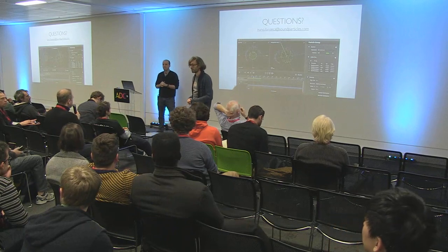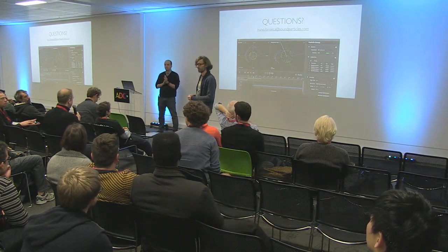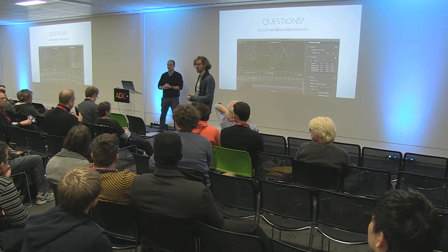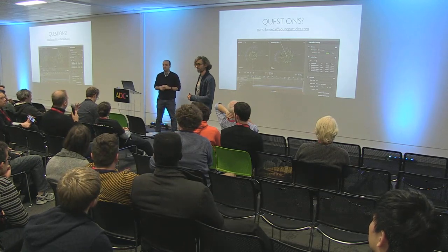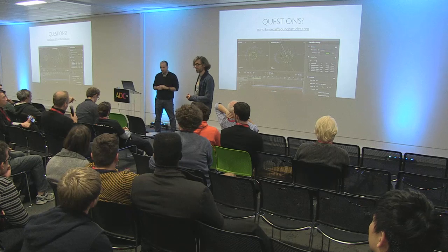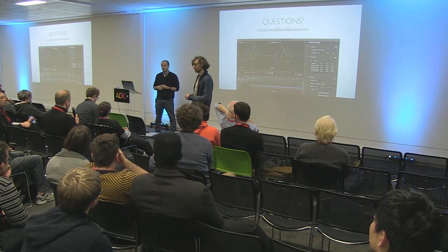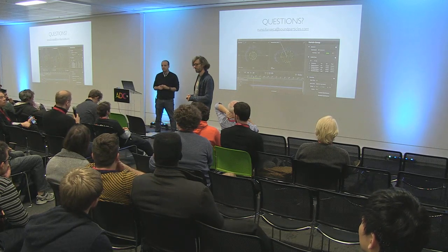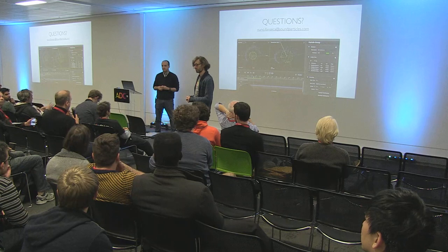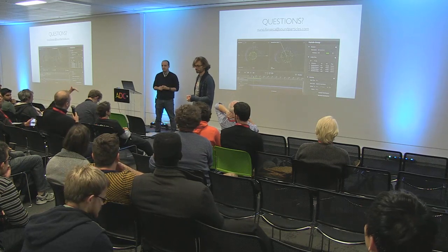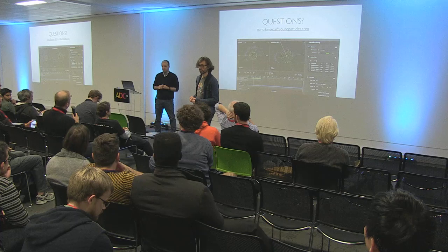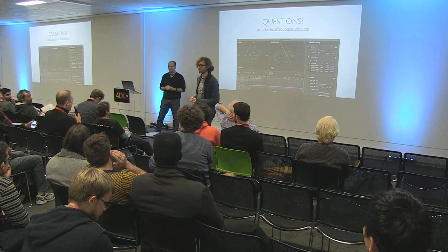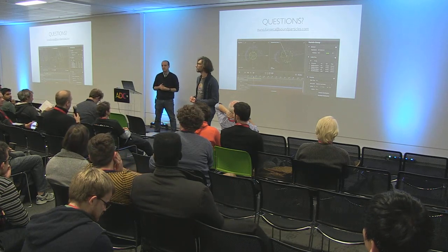Thank you very much. Very interesting talk. I have a question. I'm not sure it will be interesting for everyone, so if not, please let me ask afterwards. But what was always bothering me: you mentioned in the beginning this panning law, which is kind of linear with a -6 decibel drop. I know this explanation works perfectly for crossfading, and I also know it works in practice for panning, but I always thought that in panning you would basically apply gains to the same signal, which means the signal is 100% correlated with itself. Then I would think that not the powers will add, but the amplitudes will add, and actually you need linear crossfading. I know it's not like this in reality, but it was always bothering me, why?